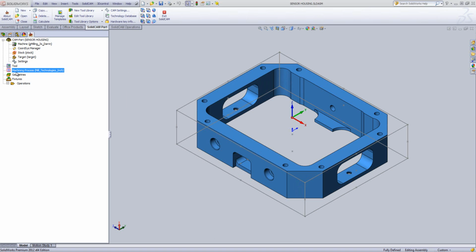The Geometries folder is an empty container box that houses items that are not currently being used in the system. Some of the items may include a profile that was chained and named but later discarded. The profile will still exist until you delete it from the Geometries folder or use the Cleanup CAM part at the end of the project.